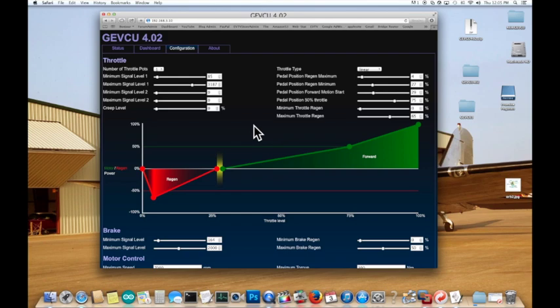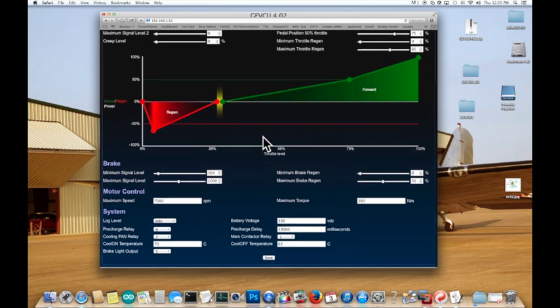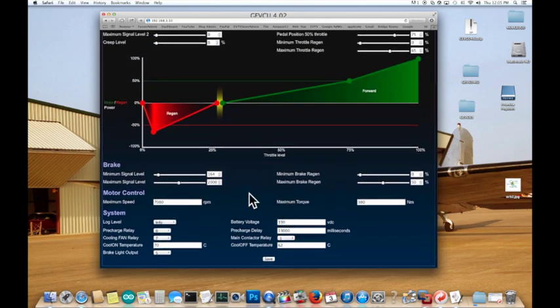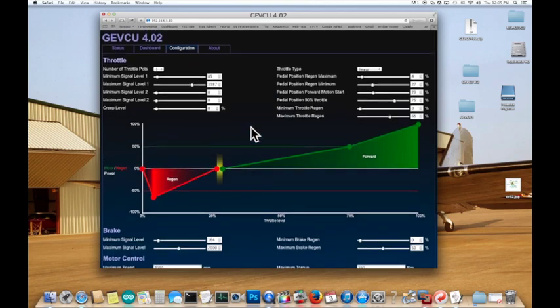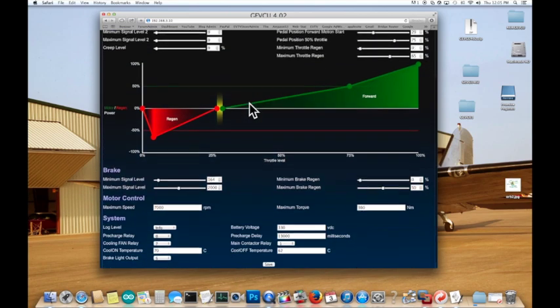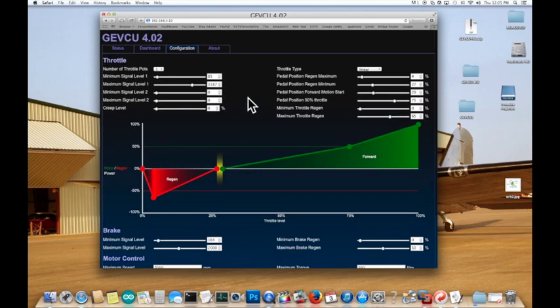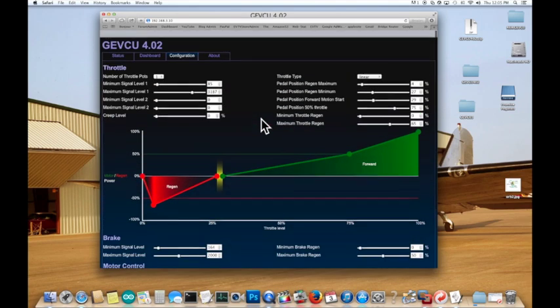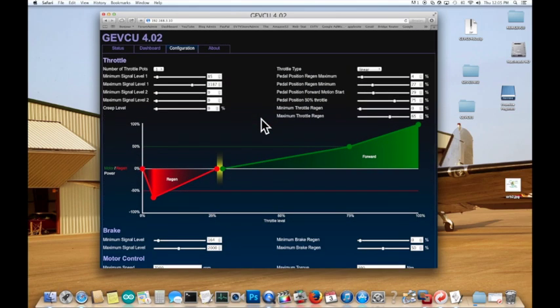And so sometimes you have to simply enter the values a time or two to get them written into the EEPROM and overwrite the previous EEPROM's variables. And that's kind of a flaw in the system. But that's a little tip on don't be alarmed if your configuration gets a little hosed up on a software upgrade.